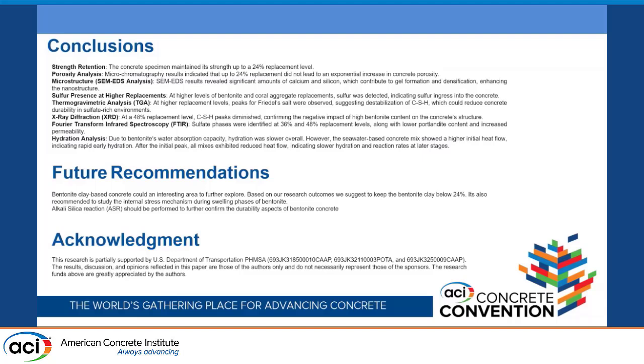The microstructural analyses like SEM-EDS, XRD, and FTIR showed that at higher dosage of the bentonite clay, the presence of sulfate ions was evident in the concrete matrix, which shows that there was foreign infiltration into the concrete, which could possibly deteriorate the long-term durability of concrete.